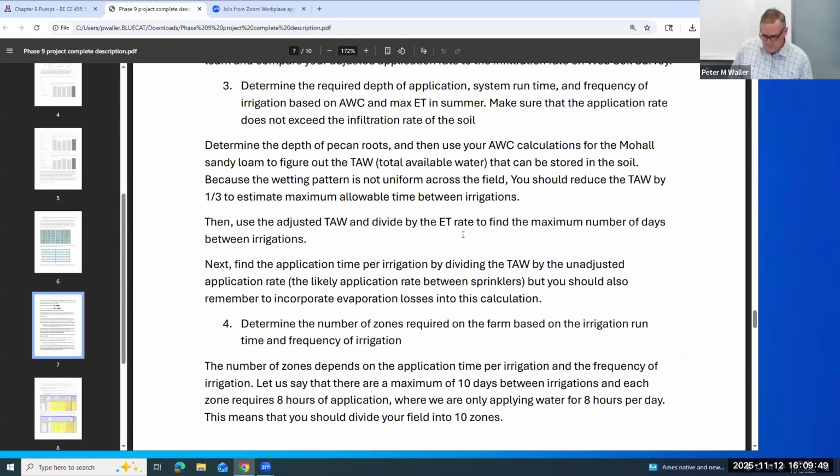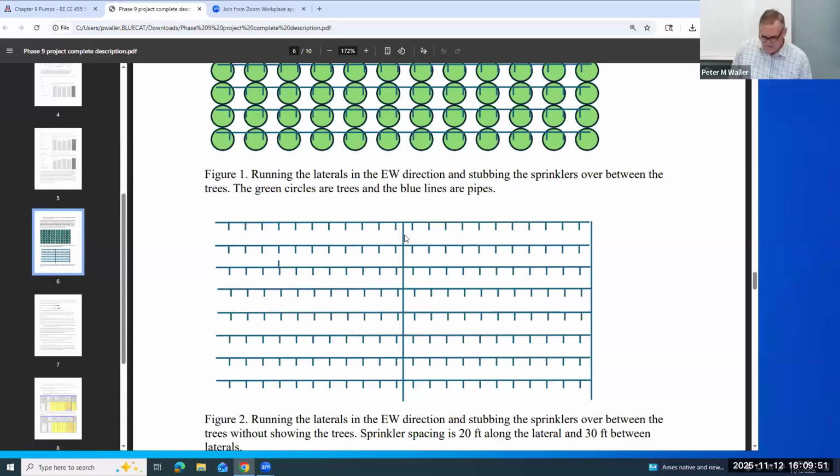And the submain, that's these pipe sizes. Okay, so it's 40 feet between laterals. No, 30 feet. So that would be 9 meters. And then I would design, and I have like a 0.02% slope here. It might not be important, but remember, you have pressure loss along the laterals, but you also have pressure loss on the submain.